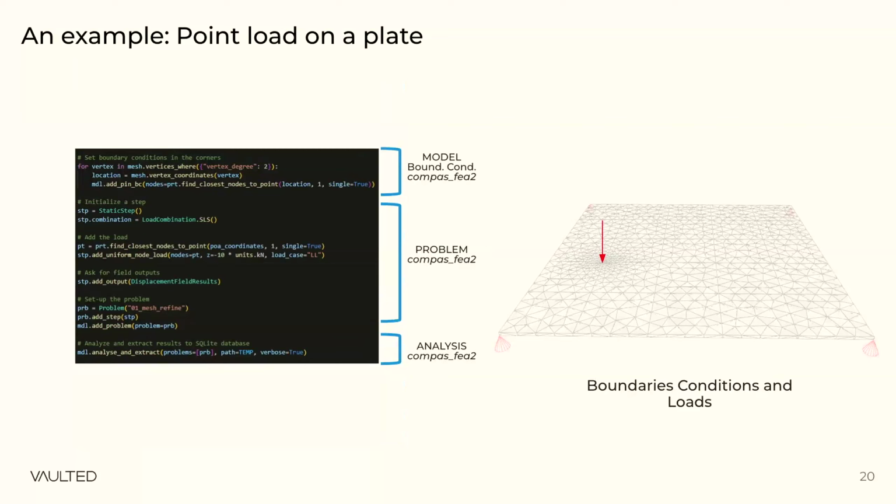Then I define all the material, the boundary conditions to my model. And then I figure out what is my problem. So there is just like a punctual load that is applied on my model mesh. And you can see also that thanks to my script, I detailed my mesh to be more detailed around the punctual load.